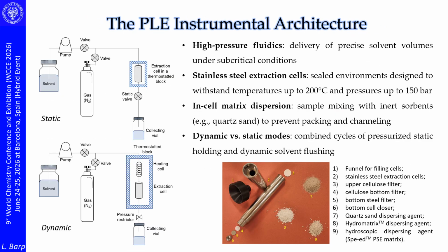Before evaluating our specific case studies, let us focus on the instrumental architecture that makes these thermodynamic parameters possible. As shown in this fluidic diagram, the PLE system is built around a robust high-pressure hydraulic network. A pump delivers the solvent or solvent mixtures into a stainless steel extraction cell, which is tightly sealed and housed inside a temperature-controlled thermostatic oven.